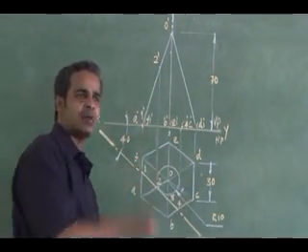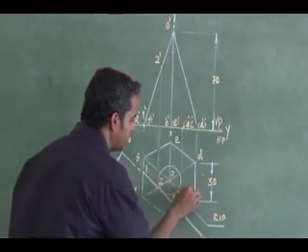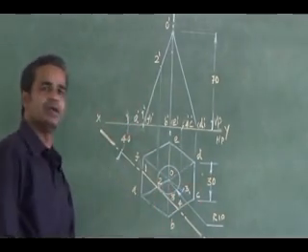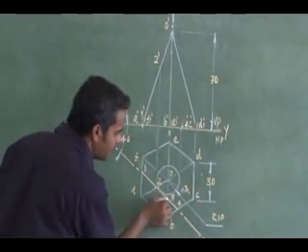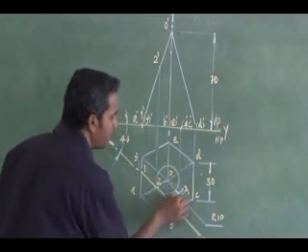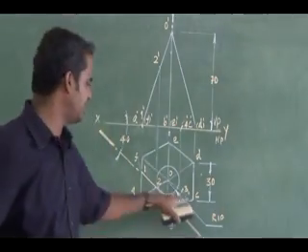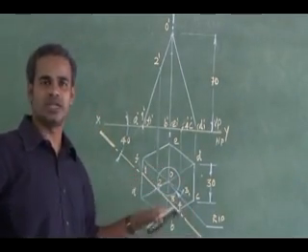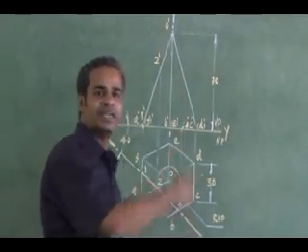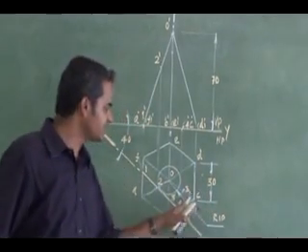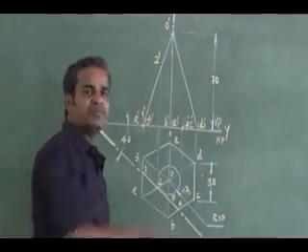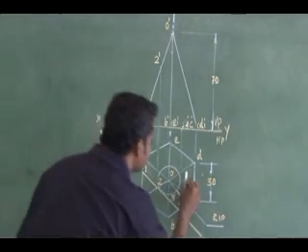So this is an arbitrary location, so I can mark it as 3 dash. I am just rotating this, marking it to another extreme slant edge, OC. Now this can be projected to OC. So OC is a slant edge in the front view. So this 3 dash.